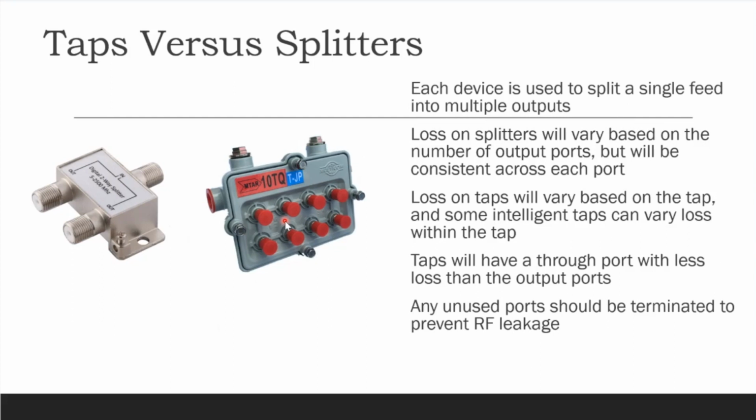So it's going to limit your ability to damage your own equipment, and it is also limiting your ability to broadcast interference and RF leakage. So you do want to make sure you're using terminators, but we do recommend metal terminators just because they're a little bit better than what you've got here.